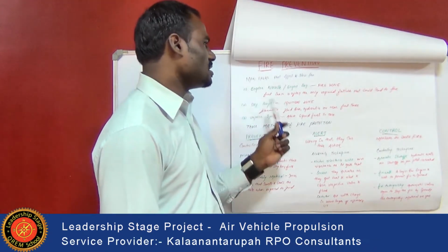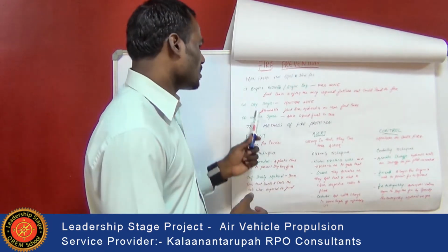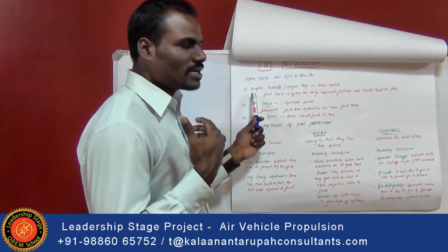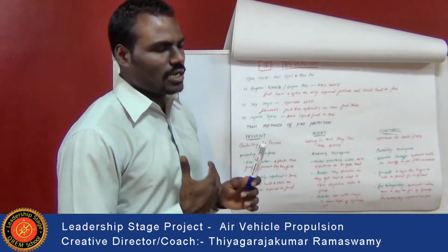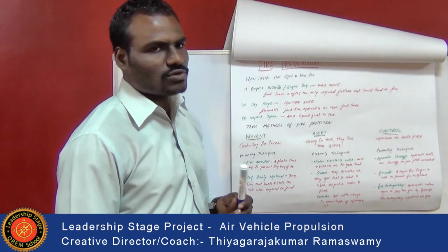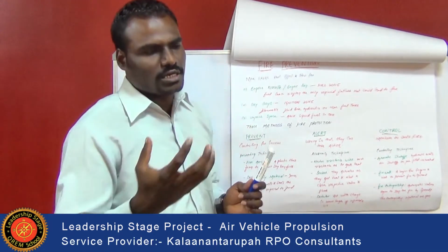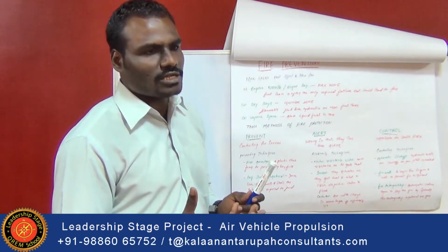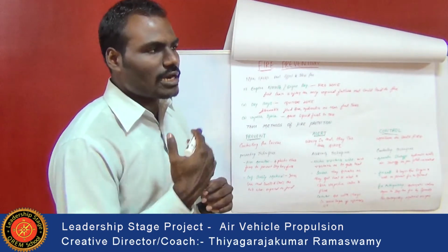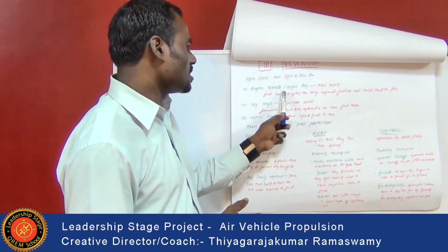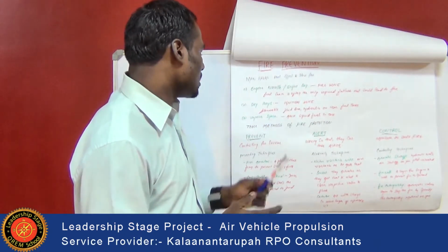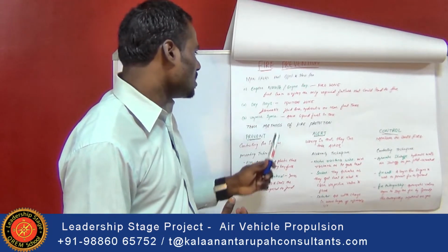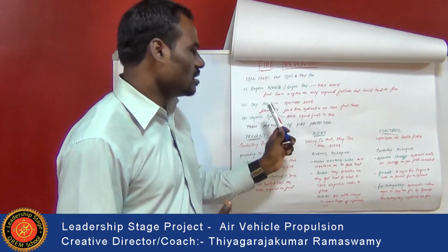The main areas that are affected and start fire in the aircraft engine are the engine axis structure, where we will be exposed to fire due to the air coming inside the nacelle structure, as well as the temperature of the exhaust gas which is released, so that the fire occurs at the nacelle structure, otherwise called the engine bay. Another part where we may get fire is the dry bay, that is the ignition zone, which is shown here.